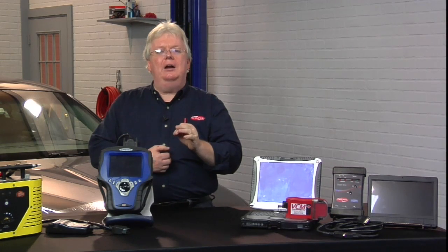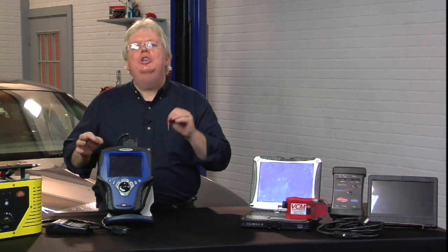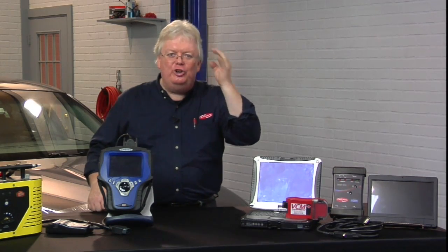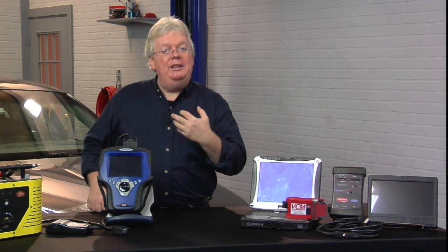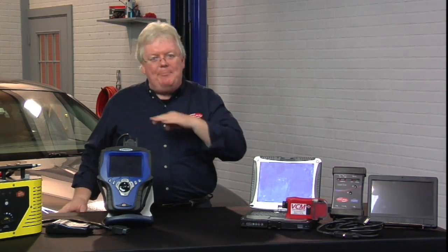We're looking for misfires. As the old saying goes, just because it doesn't pass a test doesn't mean it's broke. If it's not getting a complaint that's germane to what you're working on, you need to overlook a lot of information you'll see in Mode 6. This is part of the discernment that takes a little bit of training and experience to wade through. Otherwise, it can be a bit frustrating. So remember, if it's not pertinent to your customer's complaint, just weed on past it, make notes of it, record it, so you may need it in the future to explain to your customer.